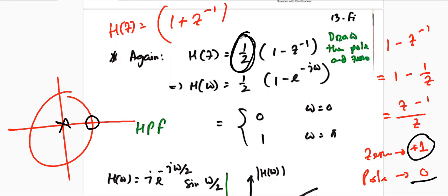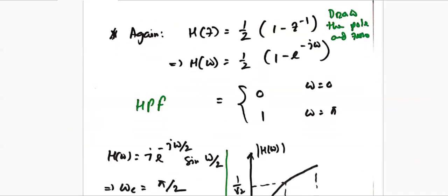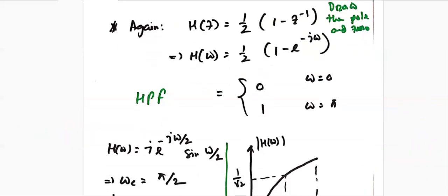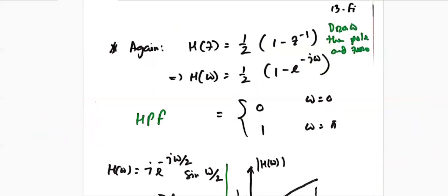Just this half is just to normalize the things, but this is very important. Otherwise, your filter might work like an amplifier as well, and that is very harmful for signal processing. Your filter maximum gain could be 1, otherwise you are in trouble. Okay, so if you allow me, I will go a little bit faster for this section.